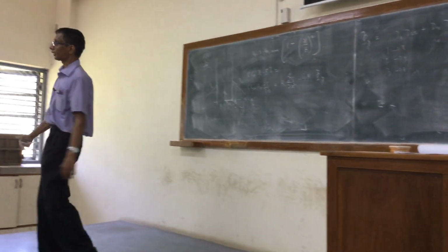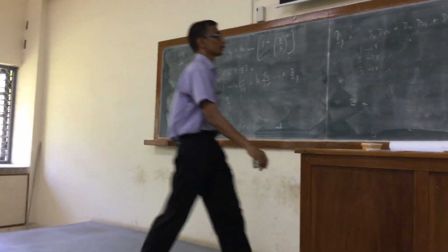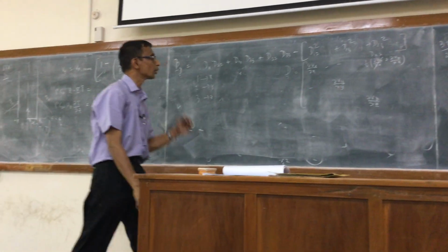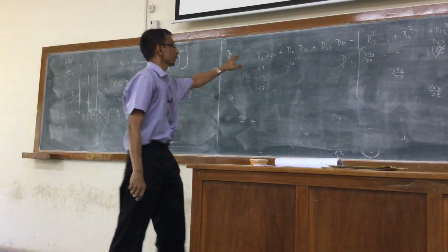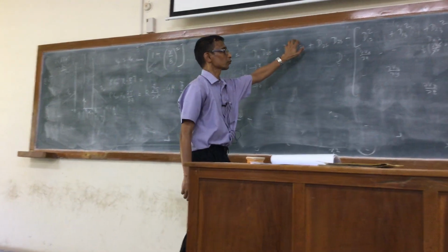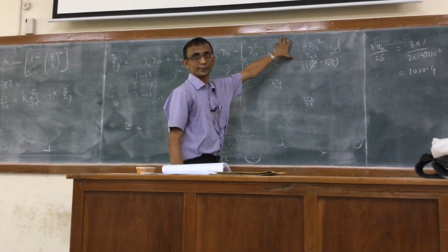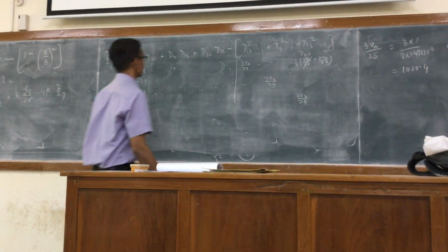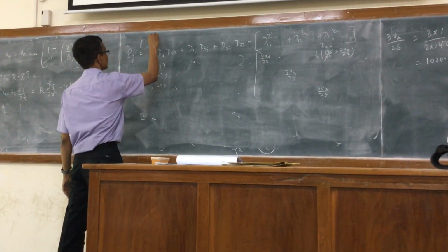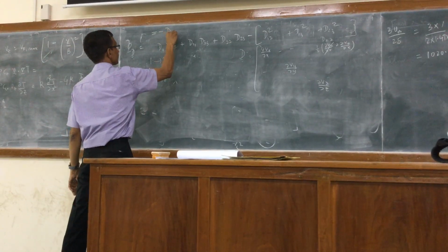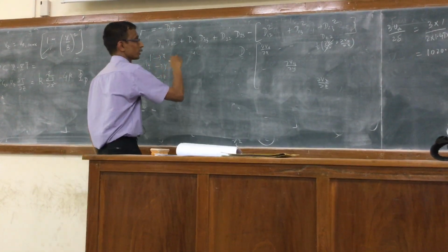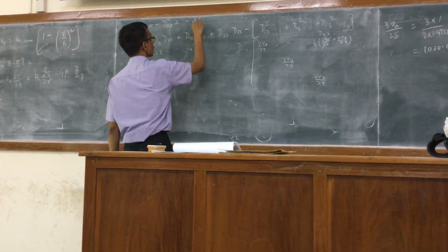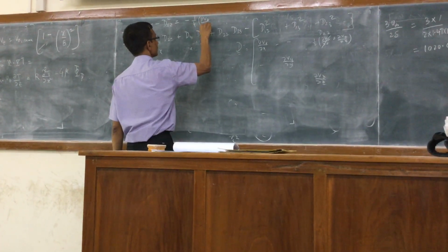Right? And so here dvz by dx is the only term that is there. So this would also be 0 because vx itself is 0. So all of these terms would vanish except this Dxz squared, right? So that would be minus Dxz squared or Dzx squared. That would be minus 1 over 4 times dvz by dx squared.